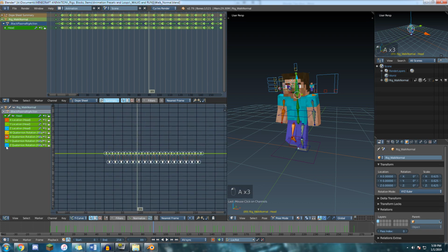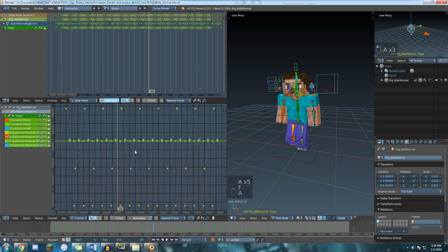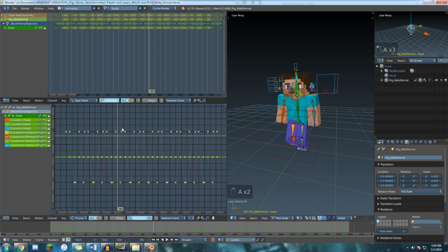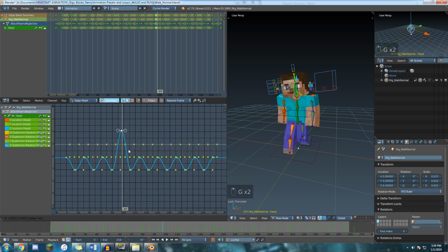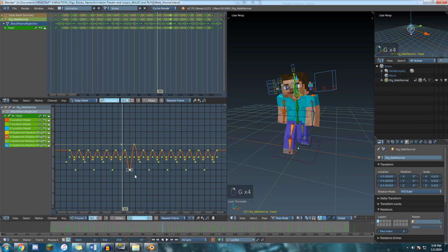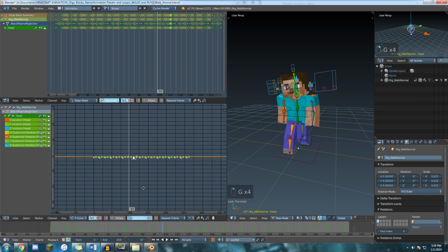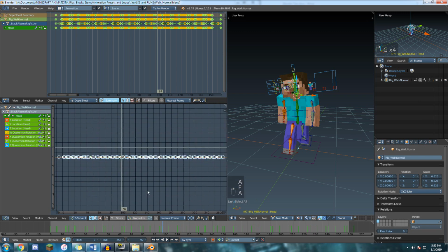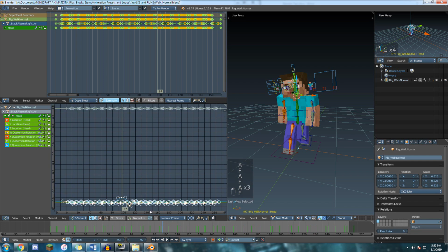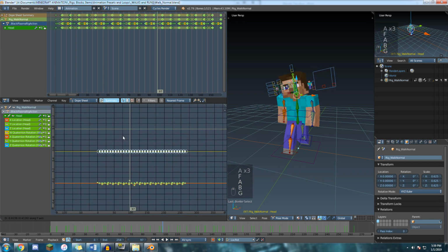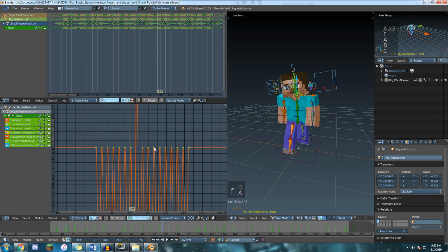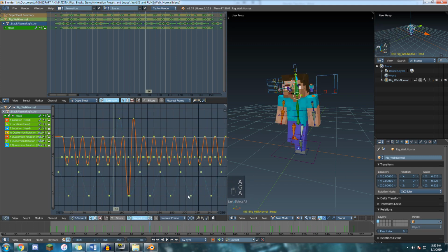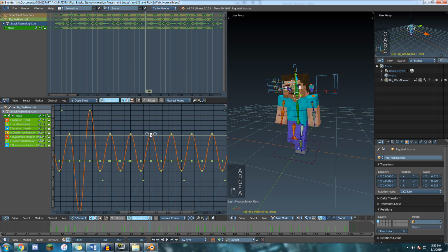Another tip is, let's say we have a few of these things on. If we press this normalize key, it will bring everything up to like a 0 and 1. So if I take any of these things and make it higher, it will normalize everything. It'll keep all this stuff within this 0 and 1. That way you're not having to constantly zoom way out for the location and way back in. As you see right here, if I have everything shown and unnormalized, we have some stuff way up here and some things way down there. Have normalize on, everything gets constrained into the -1 to 1. So normalize is handy. Box select, zoom in, grab things, move things around.